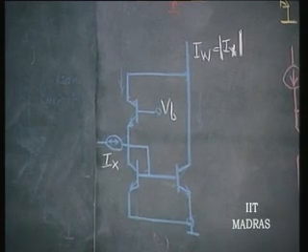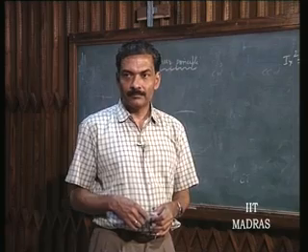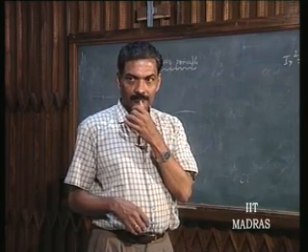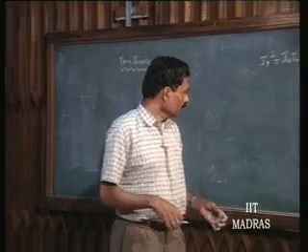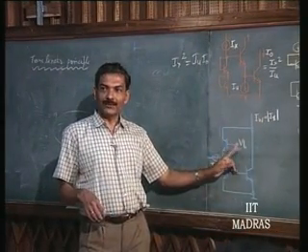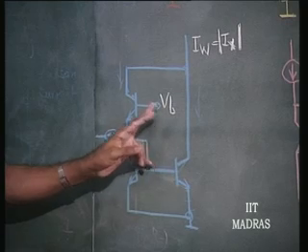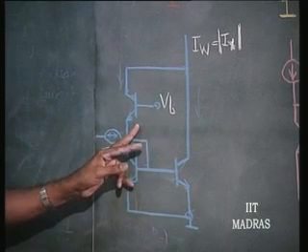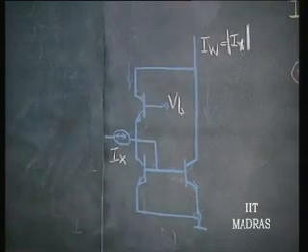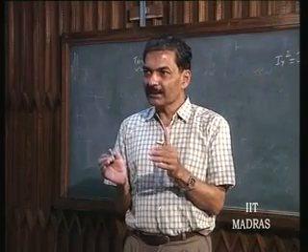There is a problem in biasing VB because the load voltage is going to determine again what VB should be. Which one? Here, this is only a bias voltage. Current is injected from this by means of a current source. So, the bias is going to be only for making the base to emitter junction conduct.